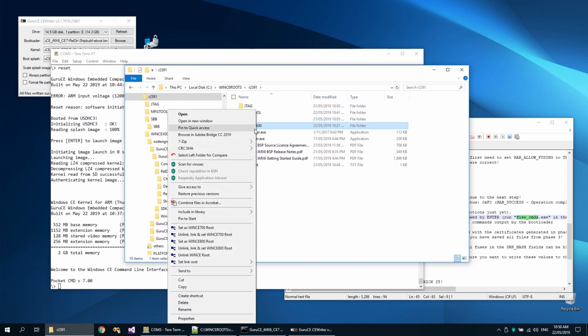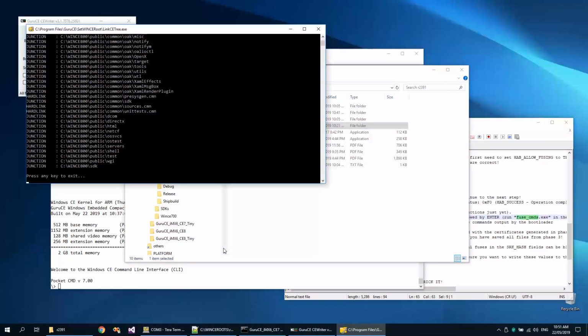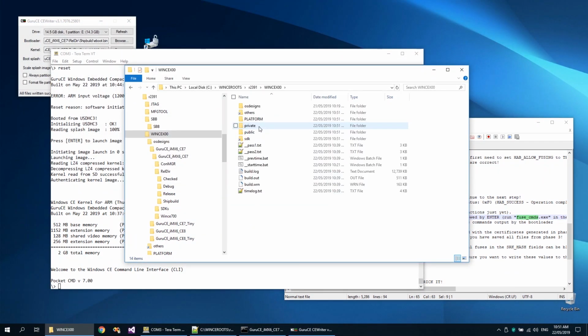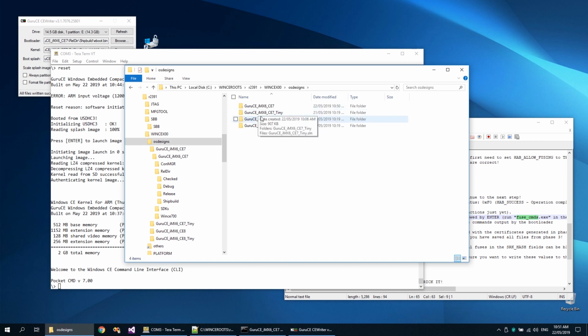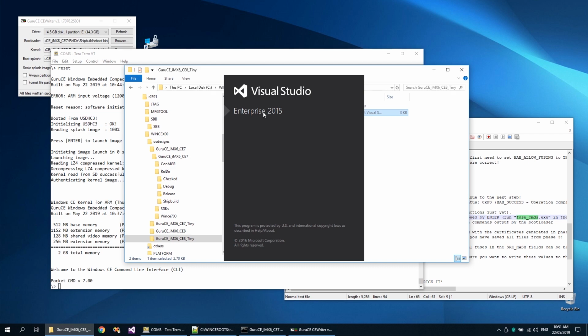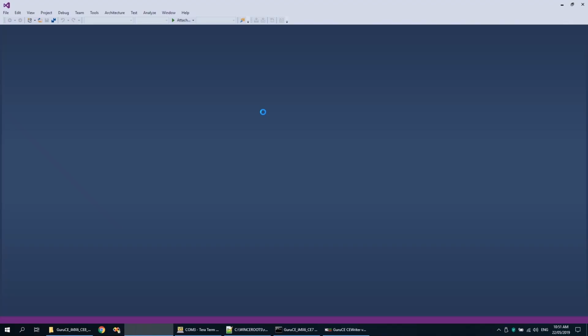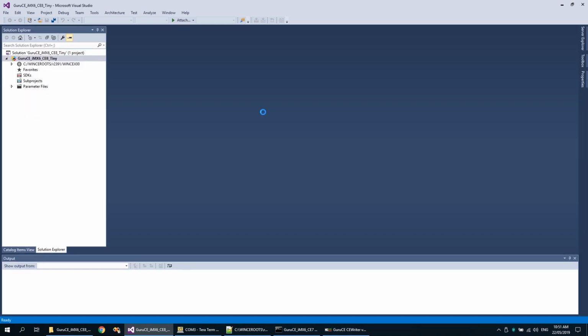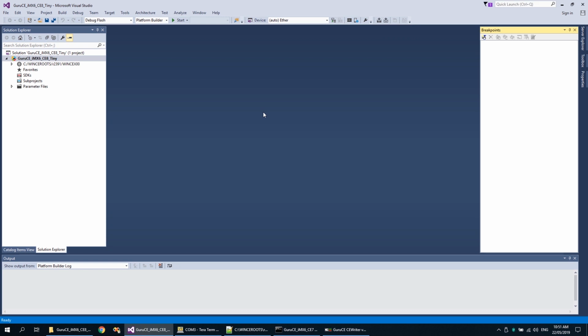Now we use SetWINCEroot to link in the WinCE800 root, and we open the C8 Tiny OS design. This OS design is configured to build a very small headless kernel. This is very handy when developing or module testing a device driver or integrated application. If you need to develop a device driver, the BSP includes a template driver that you can use as a production quality starting point for your development.